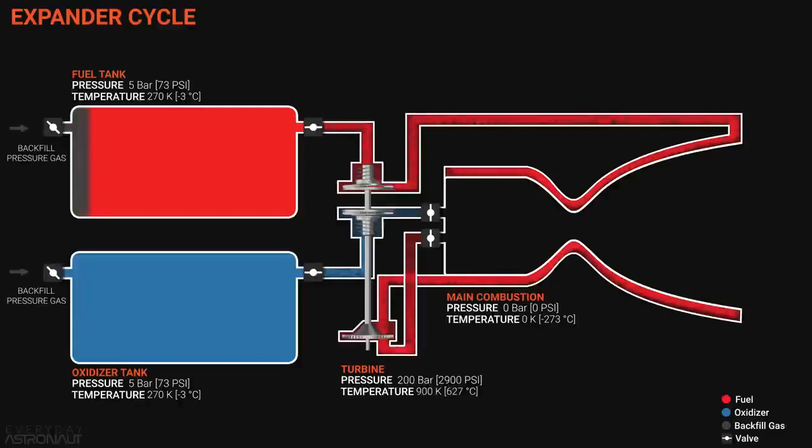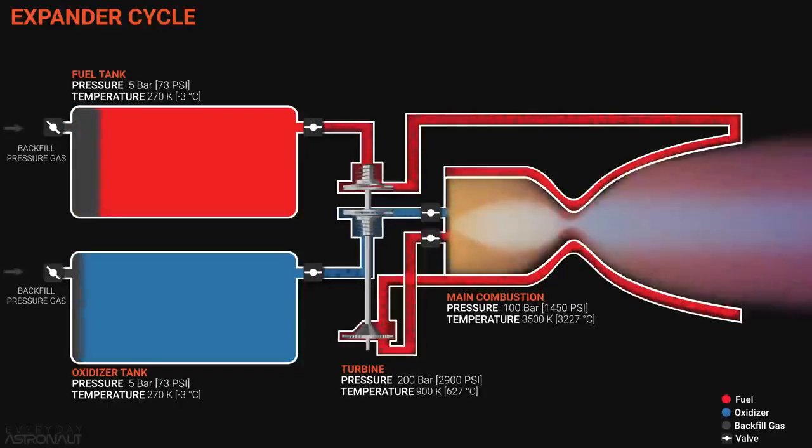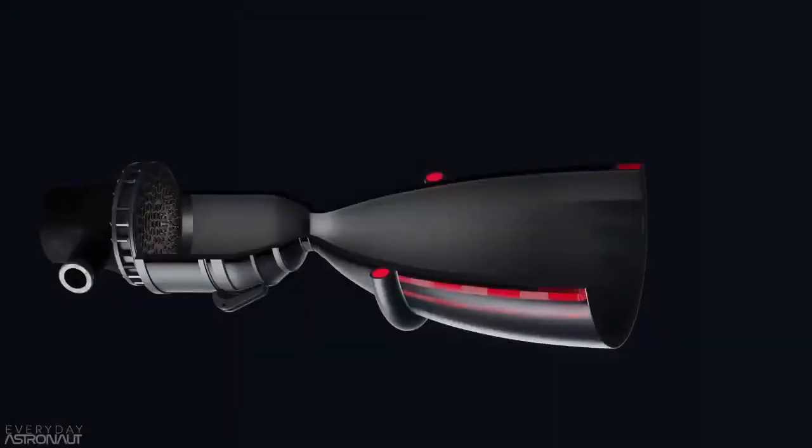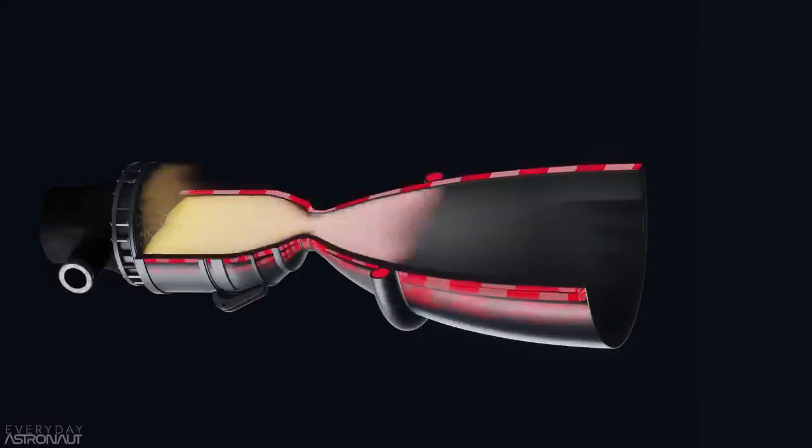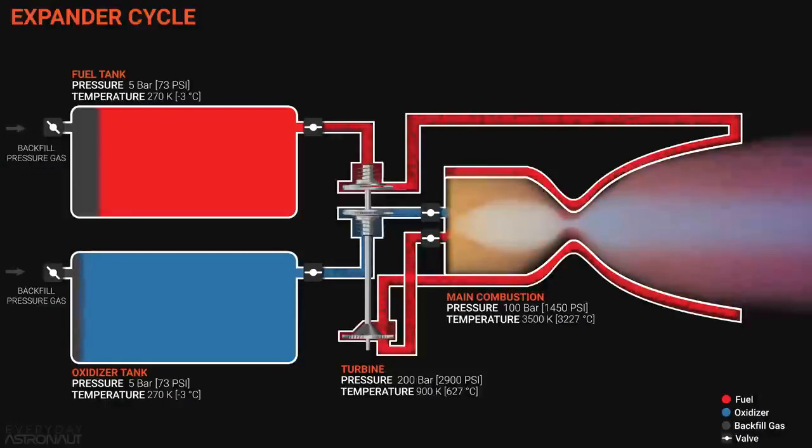Again, for those of you who watch my Why Don't Rocket Engines Melt video know, a very common and extremely effective way to cool a rocket engine is to actually pump the fuel through the walls of the combustion chamber and nozzle to help keep them cool. In the process of cooling the walls, the heat from the combustion chamber will be transferred into the fuel, where it will absorb some of that heat energy.